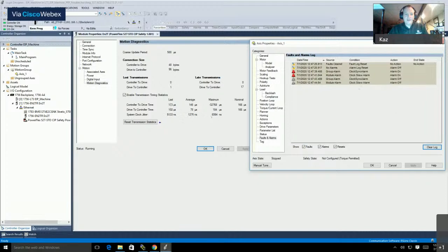Look at our clock jitter. 7,000 nanoseconds. Is that over the course update rate? A little bit. So had our drive been running, it's probably not running any longer, right? So the instance of just disconnecting the master because the master clock was in the other panel caused that to happen, caused that to blow up. So I'm going to replug this back in. And while he's going in,